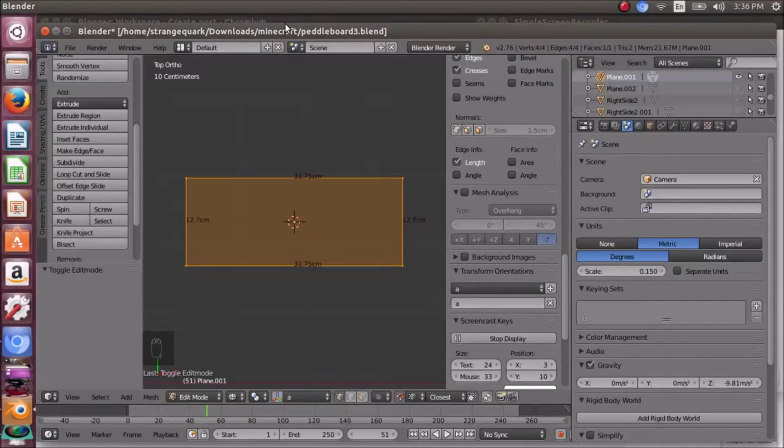For 3D printing, I highly recommend reading guides on the necessary ingredients or requirements for mesh design work. Part of that includes that your geometry is supposed to be manifold versus non-manifold. What that means is that you don't have any non-enclosed geometry. In other words, you have to have a wall thickness included with it, and there is a closed loop